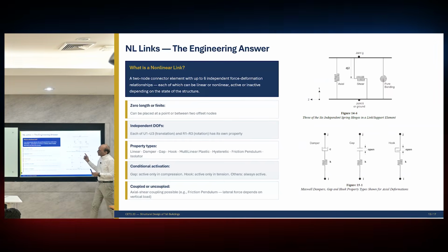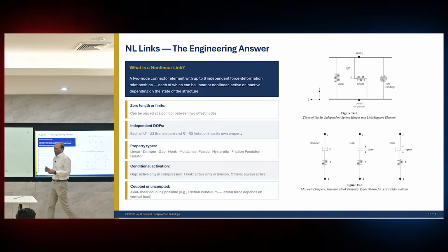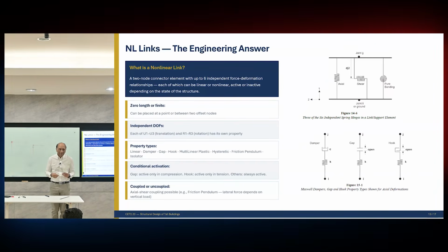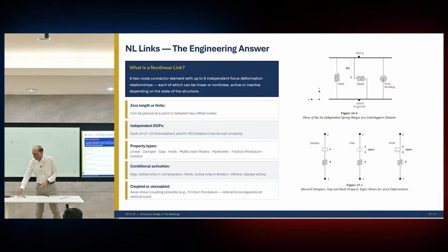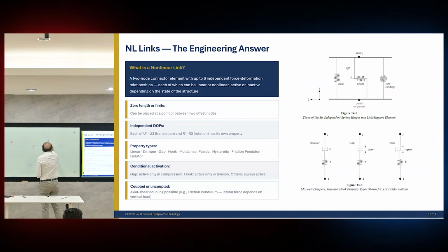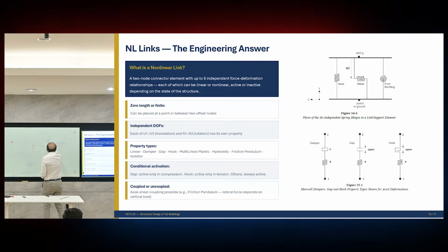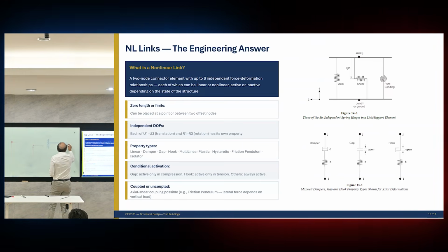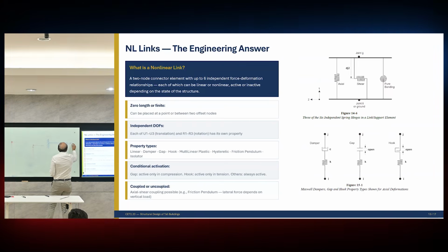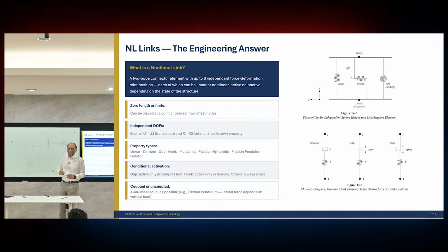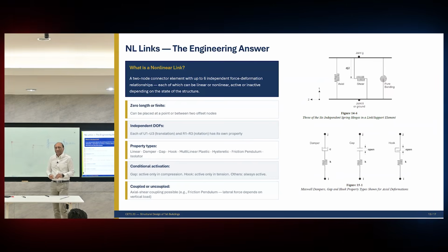So now, going back to the problem, the most interesting example of this application will be a very simple cantilever with a wall here with a gap. Let's say 10 millimeter, and you have a load here. So this is a classic example where you can use the gap element.